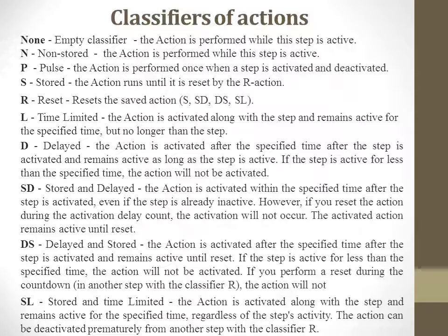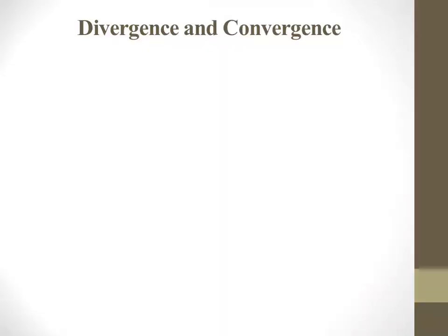The action is activated along with the step and remains active for the specified time regardless of the step's activity. The action can be deactivated prematurely from another step with the classifier R. So in this part of our lecture we discussed classifiers of actions.